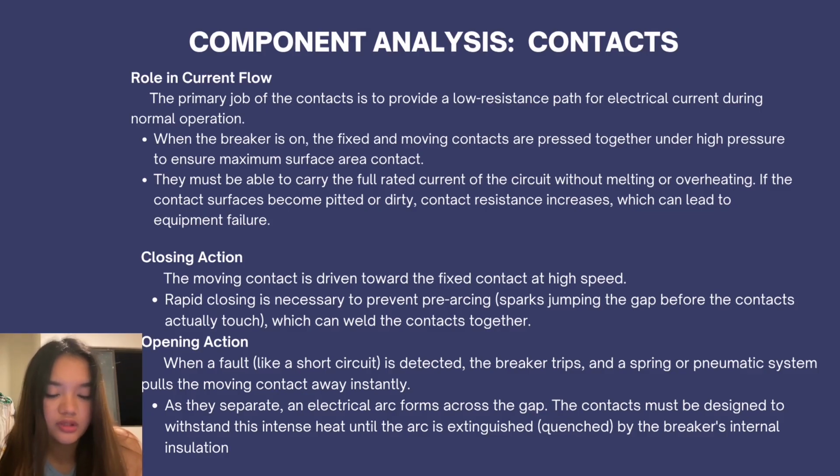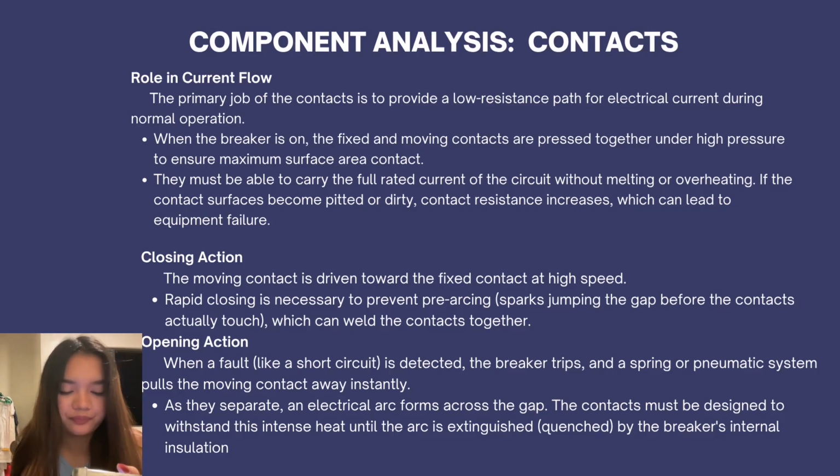Meanwhile, when it comes to heat management, they must be able to carry the full rated current of the circuit without melting or overheating. If the contact surfaces become pitted or dirty, contact resistance increases, which can lead to equipment failure. The opening and closing action.